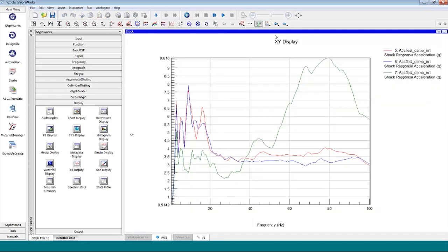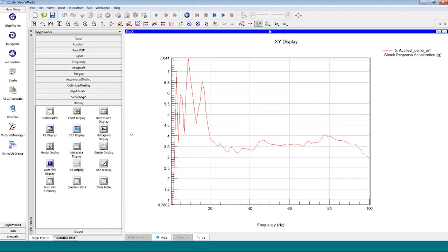We had three channels of acceleration. From this point forward, we're going to do all of our calculations separately. The X channel, the Y channel, and the Z channel will all be used separately, and the reason we do that is because that's the way this type of testing is typically done. We shake in one axis, followed by shaking another axis, followed by shaking in the third axis, so a sequential playback of vibration. We're going to mirror that and do all of our calculations on separate channels. Our end goal is to create an accelerated shaker profile separately for the X, Y, and Z directions, and then we can use this as a table of breakpoints for our shaker test.